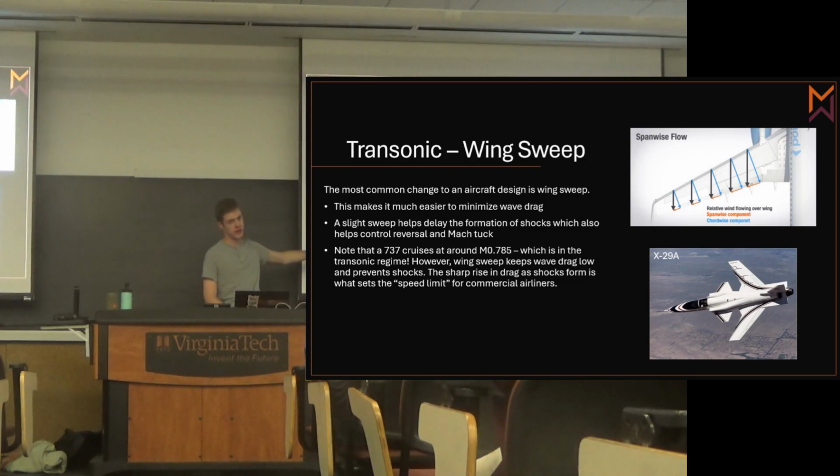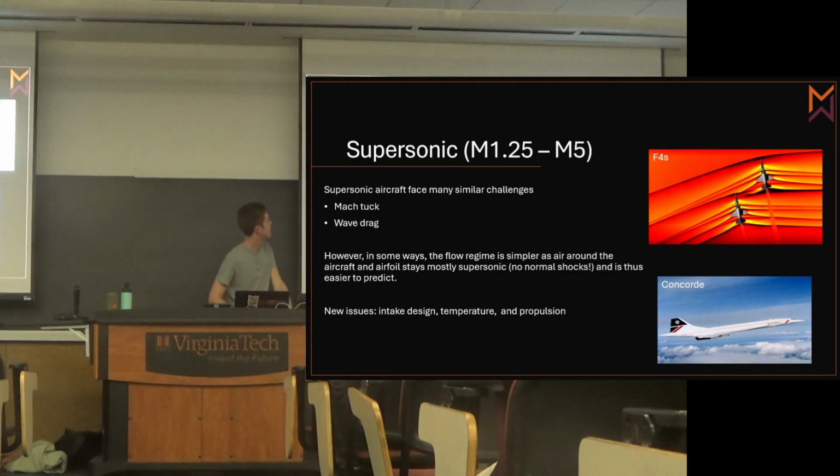Oh, there are some other benefits to wing sweep too, but a lot of them are mainly this. I think there's structural, and I think there's a case where you're trying to keep the root chord of your wing from stalling before your tip to keep roll authority and stuff like that. But they also really severely decrease the amount of lift you get out of your wing by sweeping it backwards, so there's negatives to it too. Yeah, which is why the commercials are not that swept.